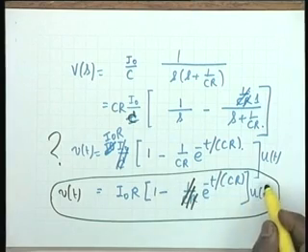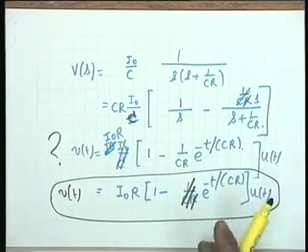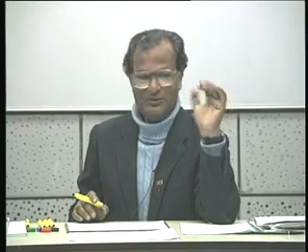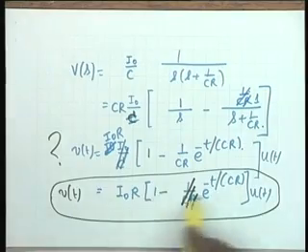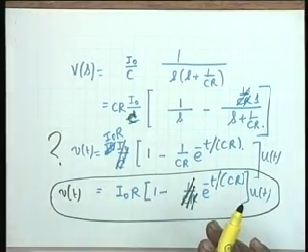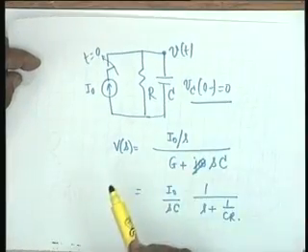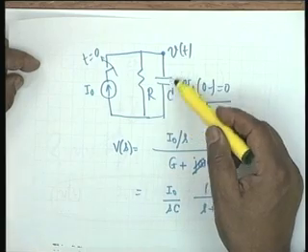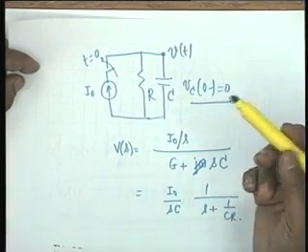Okay. Now you notice that at t equal to 0, I want to bring in physical concepts. As I said, there is no replacement for physical concepts. No mathematics, no amount of brainwashing can replace physical concept. The physical concept is that V(t) is 0 at t equal to 0. Now, does this stand to logic? Look at this circuit. Vc(0 minus) is 0. The capacitor cannot change its voltage instantaneously, and therefore V(0 plus) is also equal to 0.